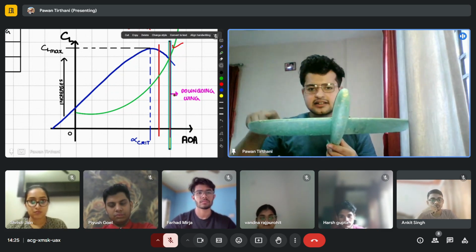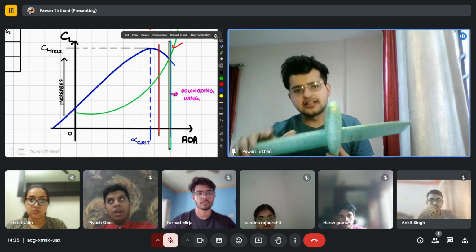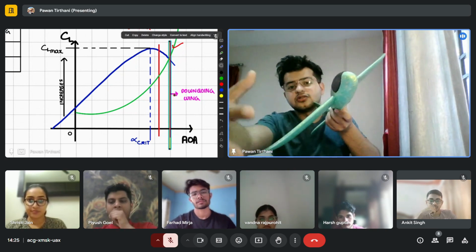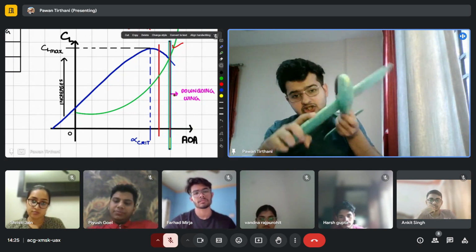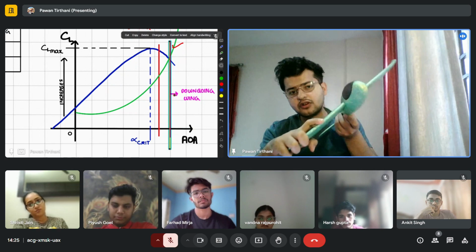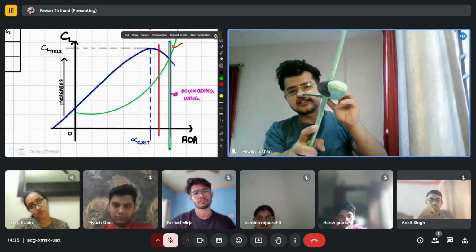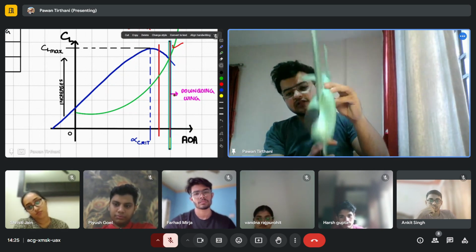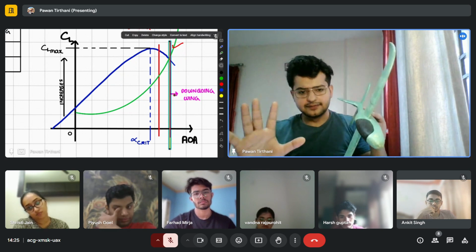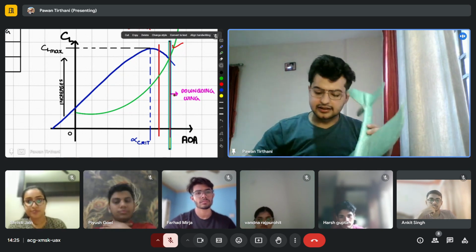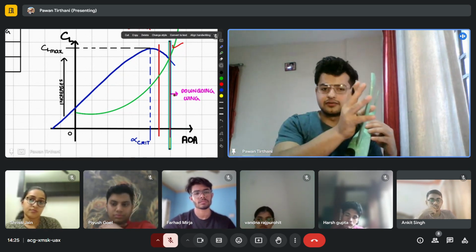Here, is the drag more or less? More. So this is going down and it is also getting more drag. So it will stop. It will not try to move forward. So it's going like this, and it is not going forward as well. So it gives resistance. Clear? Now what about the upgoing wing?